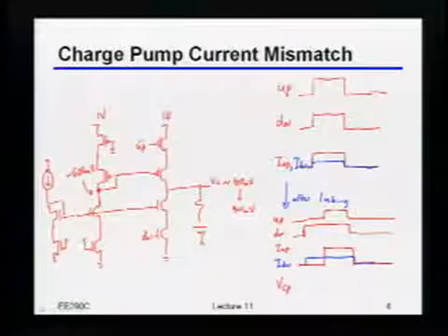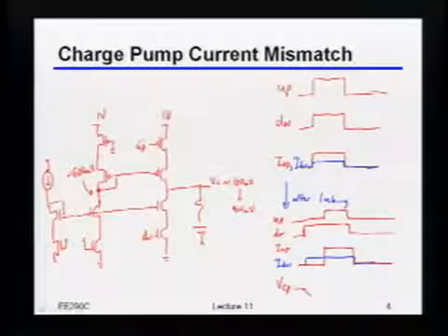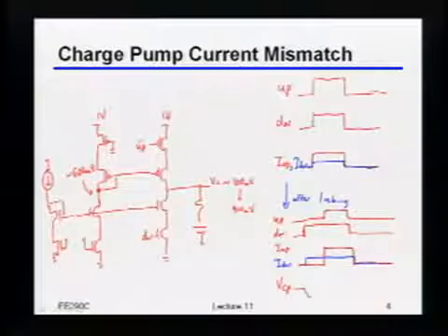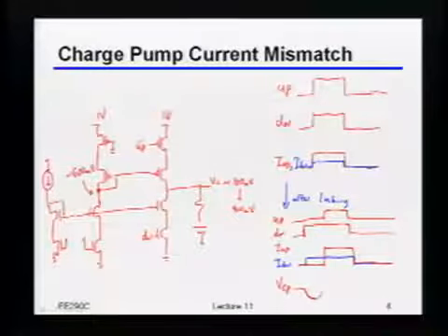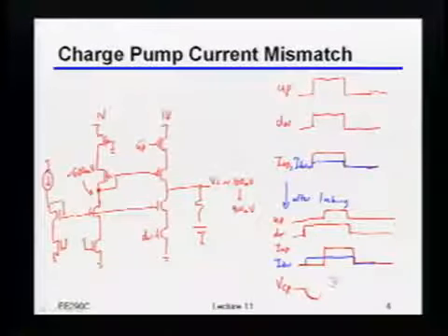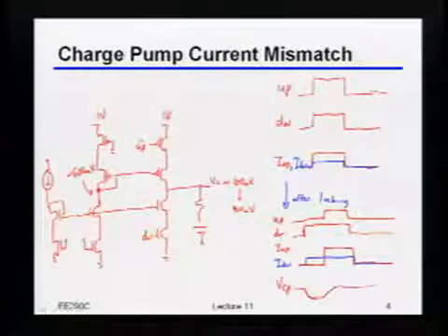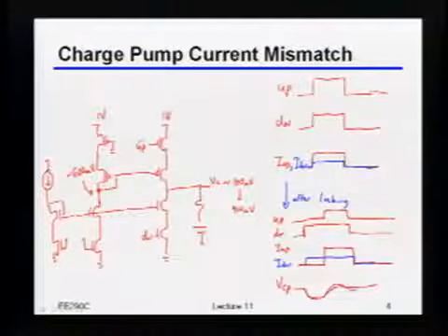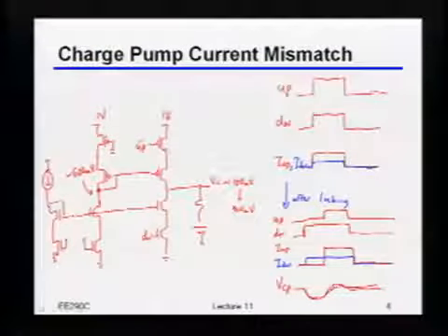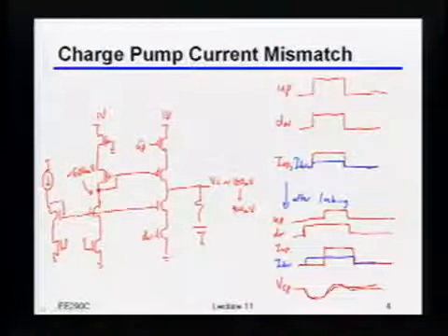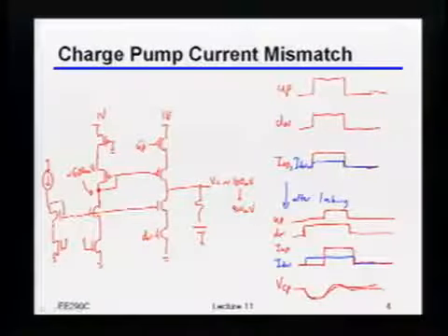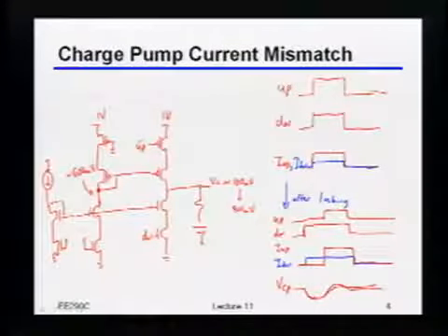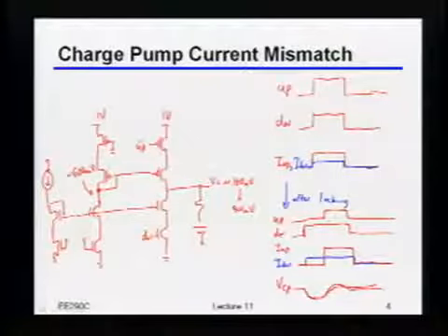So basically, every time you do this, the control voltage glitches down a little bit. My drawing's not great, but basically it glitches down and starts integrating down, and then it glitches up, and then integrates for a while, and eventually it reaches steady state, once the charges and everything have balanced out. So it's another little glitch, and long story short, it comes back to the same point. But I've created this weird glitch behavior. And by the way, that glitch happens every single reference cycle, even if I don't have any noise at all. You had a question?